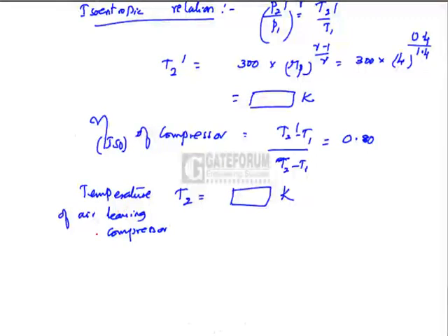Now, considering the Tmax, that is T3, which is given as 875 degrees centigrade, when converted into Kelvin we have to add 273. 3 to 4 dash is the isentropic relation.